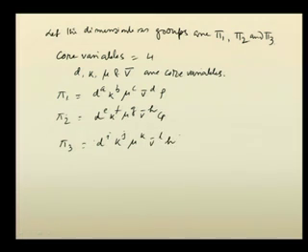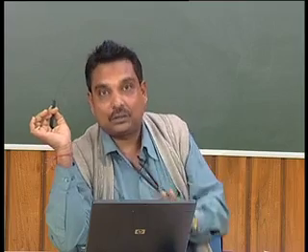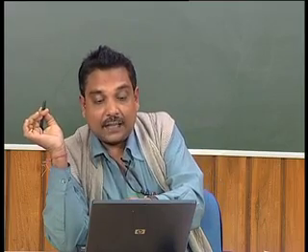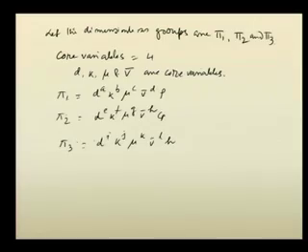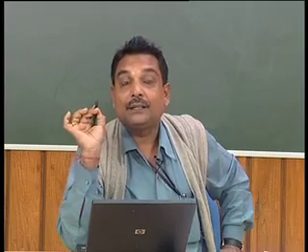So, we can very clearly understand that the core variables will be repeating in all the dimensionless groups as of now, because we do not know which is going to exist in pi 1 and which is not. The other 3 variables, rho, Cp and h, will come only once in one of the groups, and their power will be taken care of by the a, b, c, d, e, f, g, h values. So, this is a very important step.